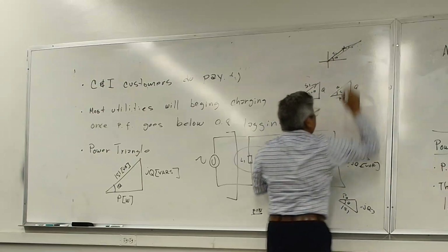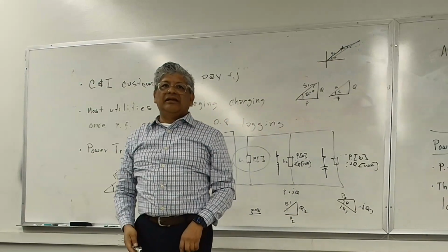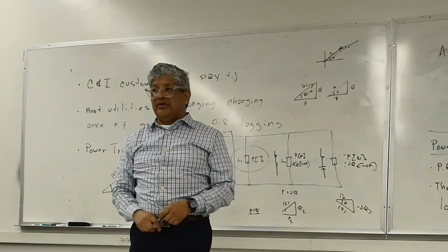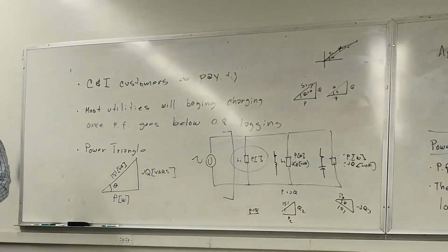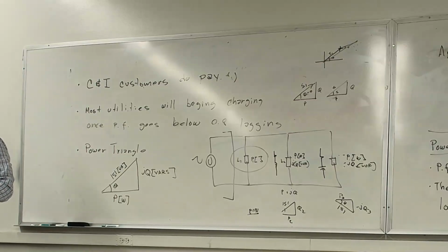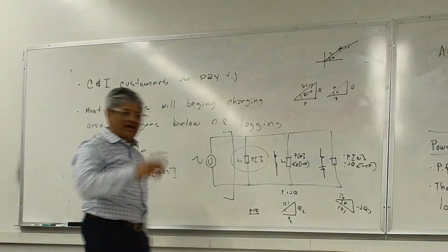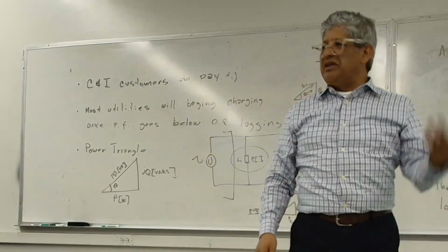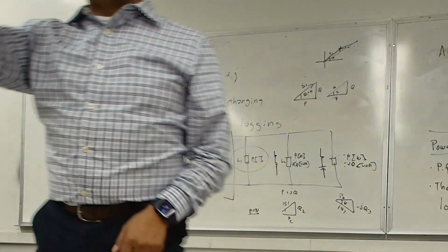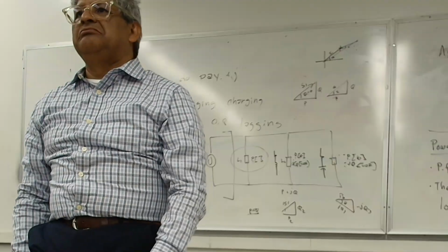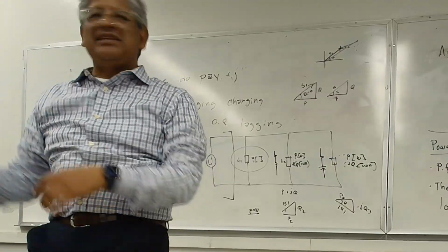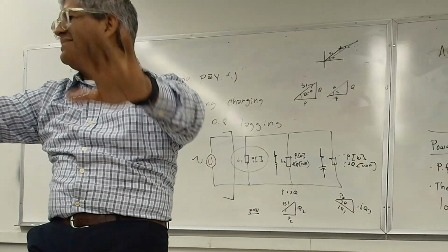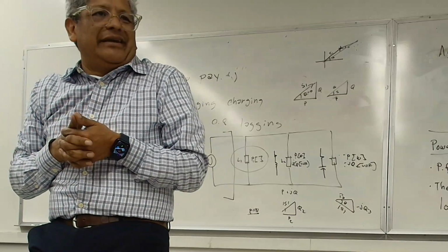Now the resultant of that, it's a vector, is the addition, the total power. It's like a vector, right? Is it easier to just add P1, P2, P3, and then add Q1, Q2, Q3, and then find the S? It doesn't matter. Whatever is easier for you. You have homework problems, test problems. You might say, I'm just going to take P and Q in rectangular form, convert that into polar form, and that gives me the S. We'll do an example. So it doesn't really matter at the end.